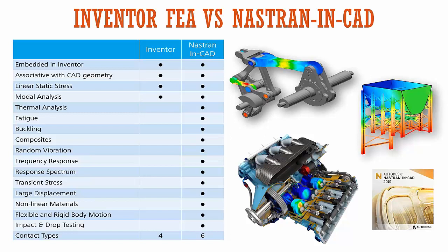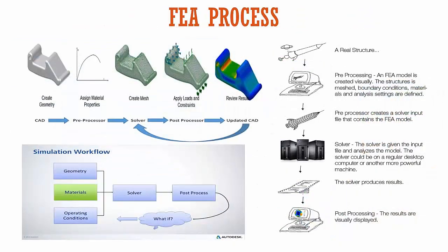There's one other thing we forgot to mention, which is hydrostatic analysis. Oh yes, I'm really sorry. Autodesk has also added hydrostatic loads, which allow us to directly apply pressure loads on the wall of a tank or something like that, which was not available earlier. It was introduced in Nastran 2020, and I'm going to use it in one of my simulations and show you how it's done.